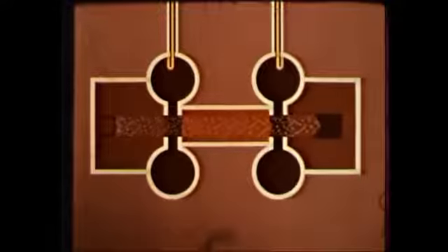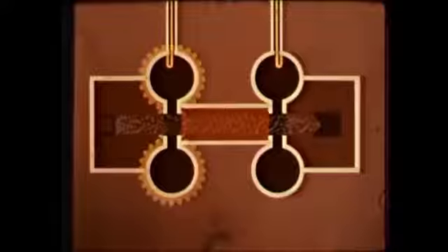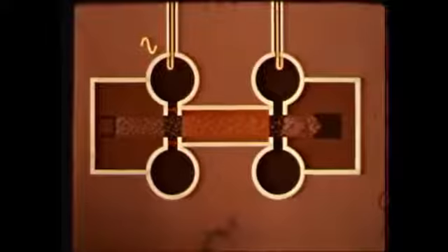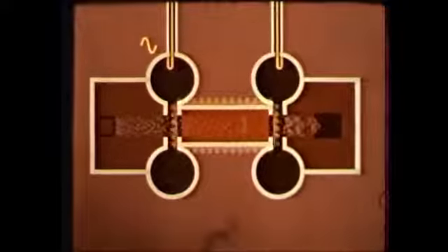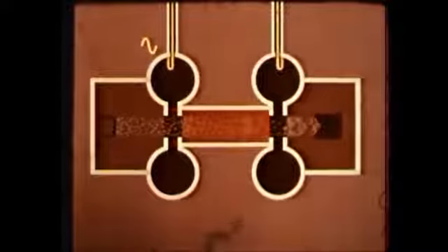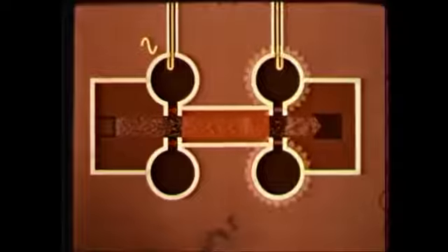Summing up the whole action of the klystron. The electrons coming from the cathode enter the first resonator with high kinetic energy. This first resonator is set into oscillation by the input signal so that the beam is modulated and bunches are formed in the drift space. These bunches, in turn, set up an electromagnetic field of the same frequency in the second resonator.